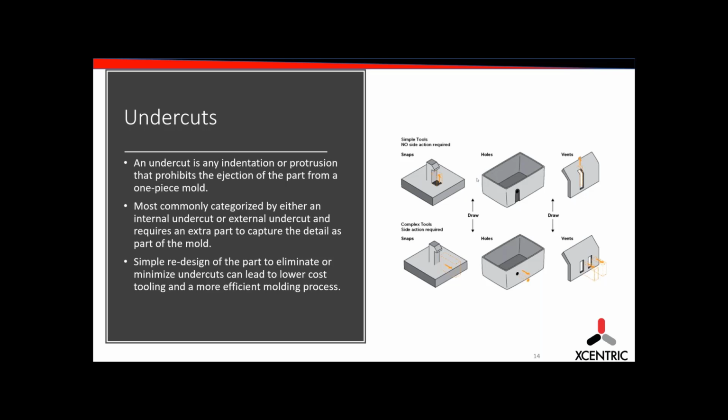Yeah. And when you cool too fast, it creates issues such as it's tougher to get the part out of the tool. The tool may shrink and lock itself onto the core. There's a lot of issues there, which, as we process these materials and we have these material data sheets and process parameters, we can usually mitigate most of those. Again, it comes down to part design and material selection.